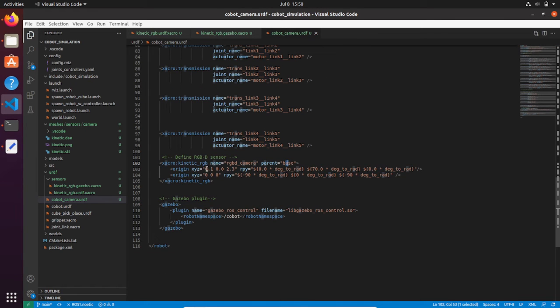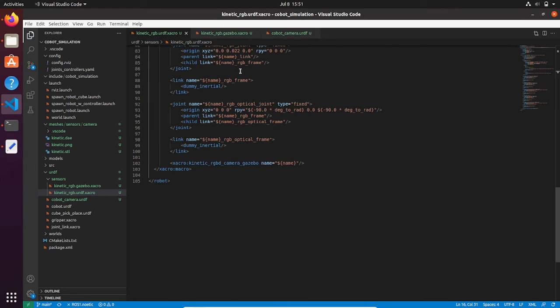So what I put here is the position where our camera will be in our environment, and here the orientation. What I forgot to tell you is that here in our urdf.xacro file we have used the gazebo.xacro, where basically we have used that macro, giving that macro the name that we will put in our urdf file.